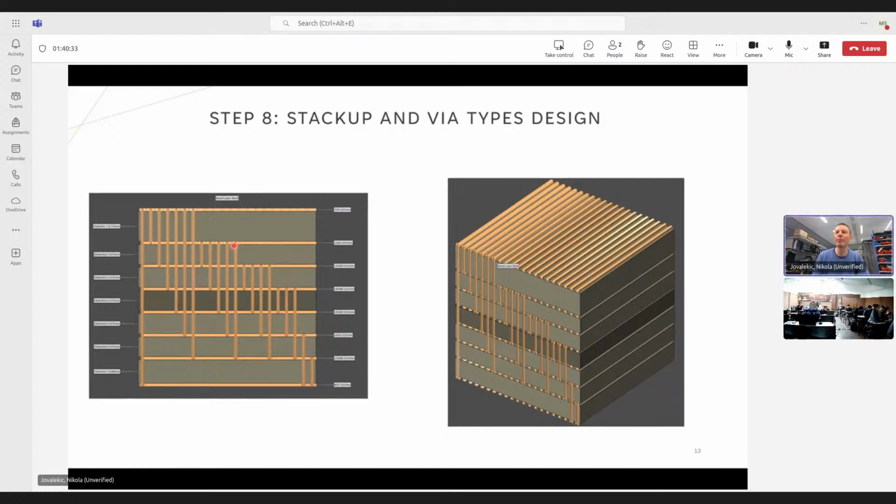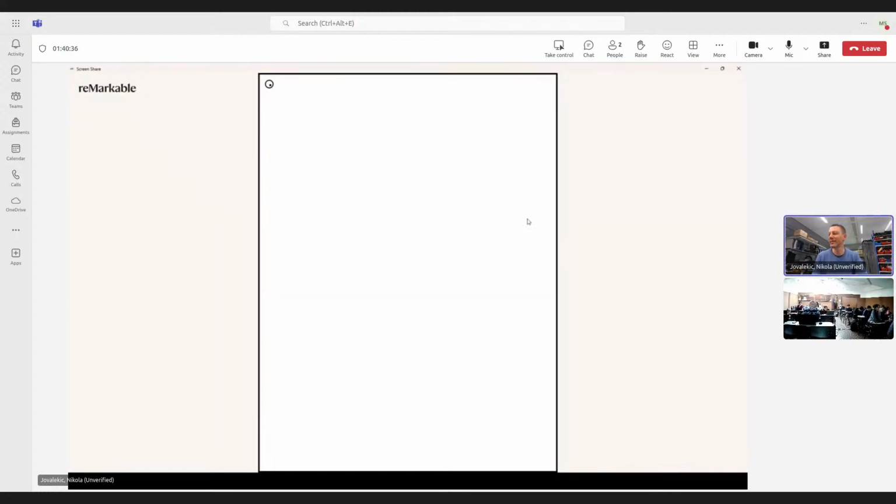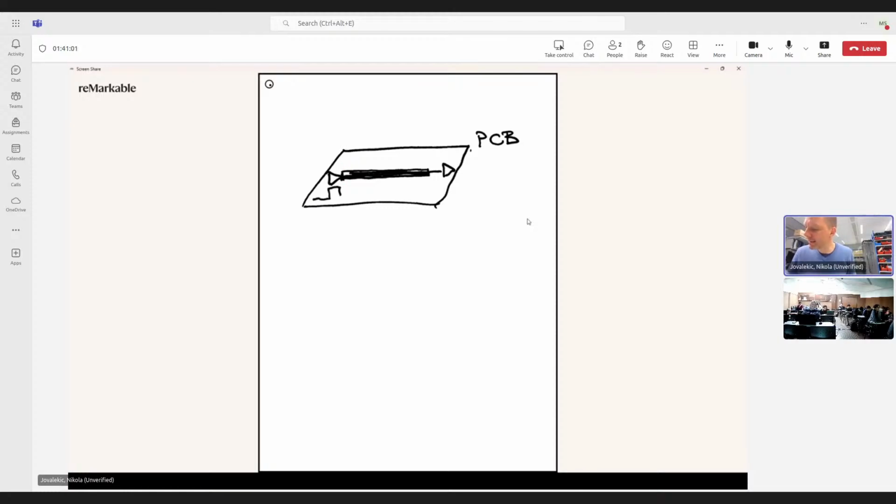When the signal propagates through the interconnect, so when you have something like this, let's say a PCB, and you have some kind of a driver, and then you have your interconnect and your receiver, the amplitude of the pulse here will be exponentially decreased while the signal propagates down the line.